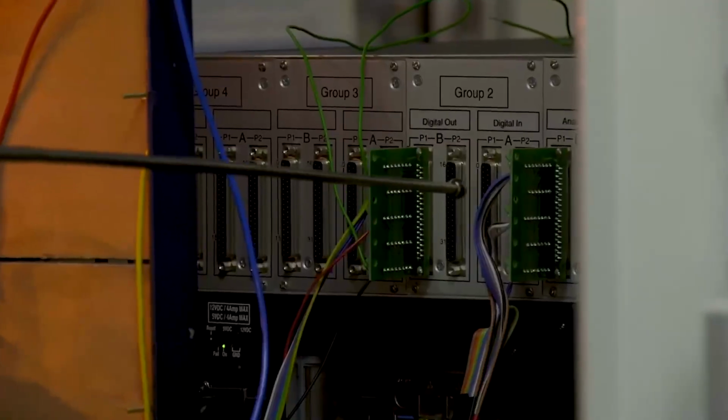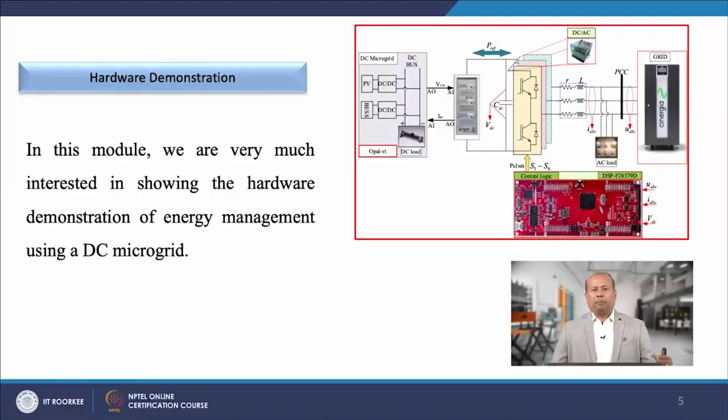To emulate the DC bus voltage through the power amplifier, the DC bus voltage is sent out through the analog out of Opal RT, scaled down to the 0 to 10 level, which is the power amplifier analog input voltage level. The power amplifier is configured to external mode, which gives the voltage corresponding to the analog input voltage value. Now, the analog output of the power amplifier is given back to the analog input of the Opal RT controller.